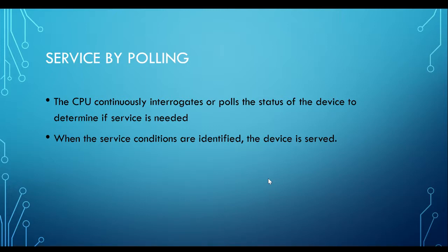Now let's give an example. Pressing the button activates a register bit, okay, and in your main program, you can keep on checking the register bit value. If the register bit value equals to 1, you blink an LED and then you go back, okay, to the main program. Blink for 1 second, then you go back. Okay. Now this kind of example is called polling.